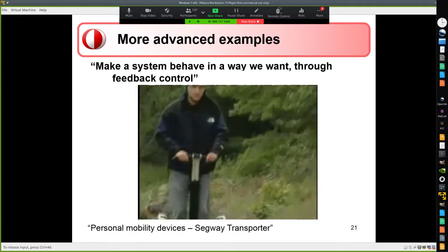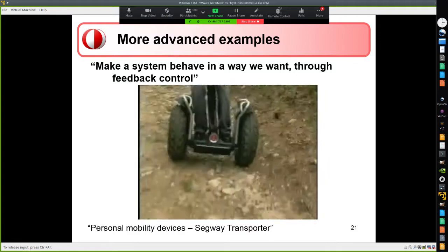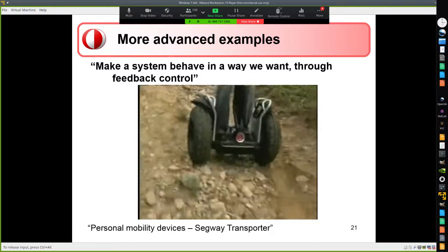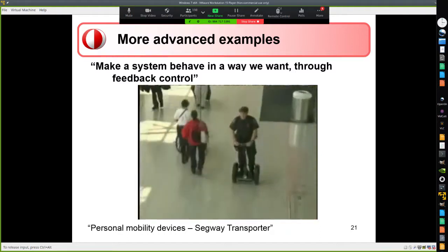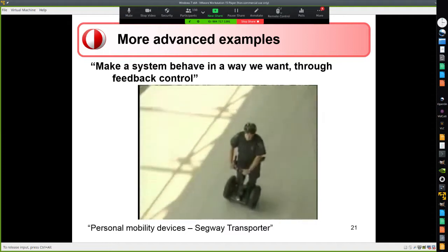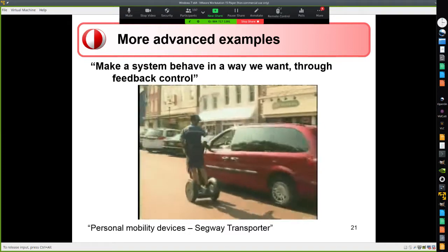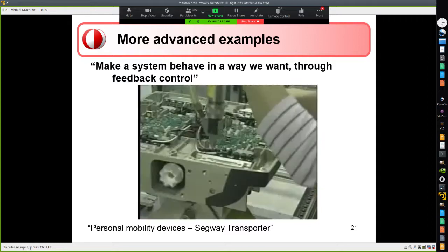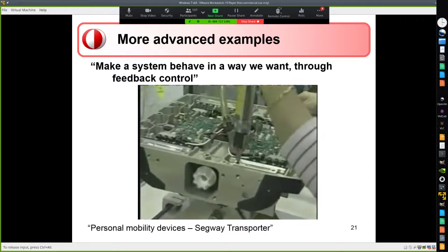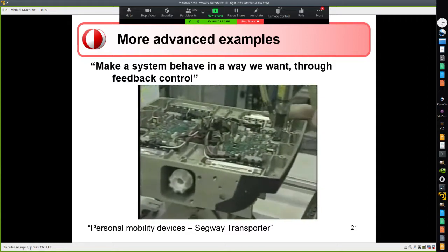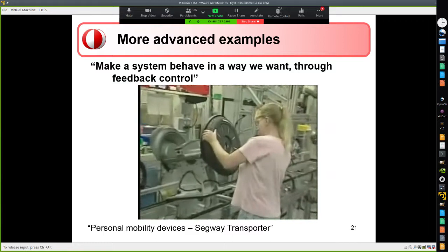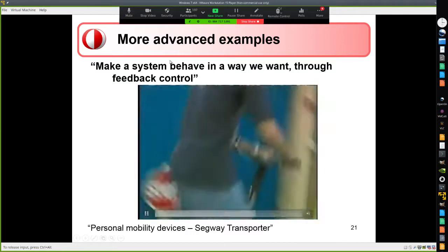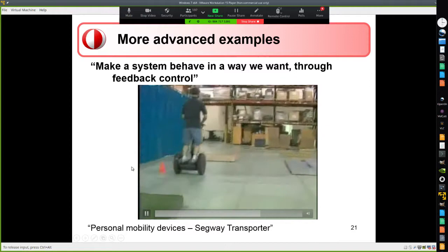In every Segway, there are two electric motors, one for each wheel. Each motor produces 2.5 horsepower. This may not sound like much given that cars can have 300 horsepower, but these motors are tiny and a Segway only weighs 70 pounds. Two controller boards provide precise computer control for each motor, and two 72-volt battery packs supply the electricity. All this technology lets the Segway perform its balancing act.